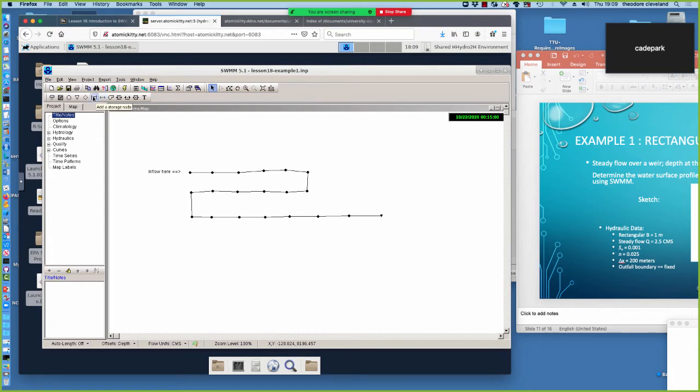We have storage nodes, which looks kind of the same as a reservoir picture because that's what the programmer used. And then we have some other things that are different. We've got a pump, we've seen that before. So the upside down triangle is called an outfall node, and this guy here is Puffy the Cloud, and that is a subcatchment element.